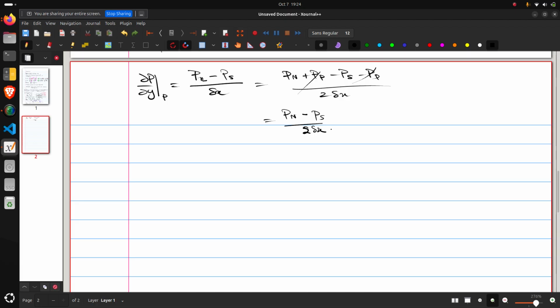Okay, so now what can be done? It is clear that if the velocities are defined at the scalar grid points, the influence of pressure is not felt properly. As you have seen in the discretized momentum equation, we have the gradient of P term. This term does not show up correctly if we store the values of pressure and velocities at the cell centers.